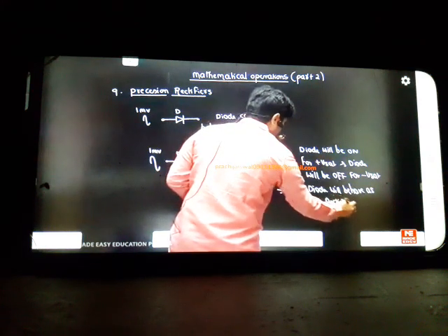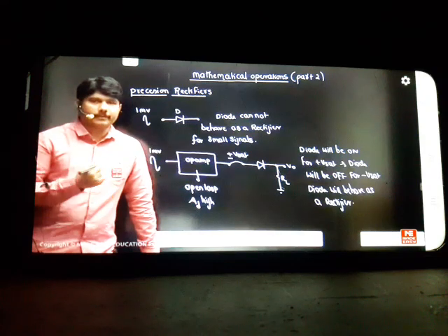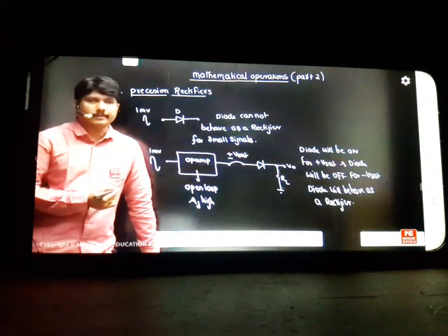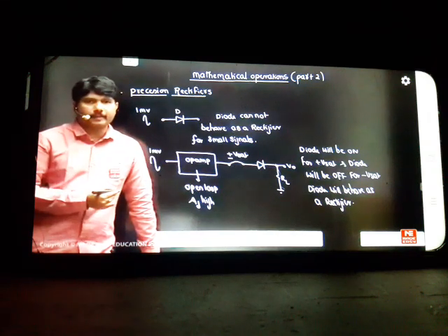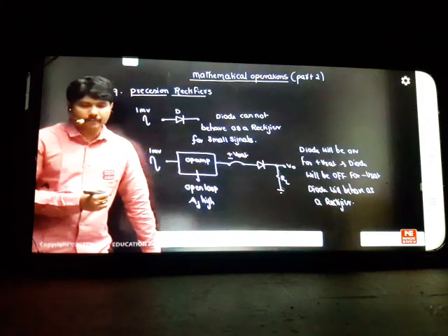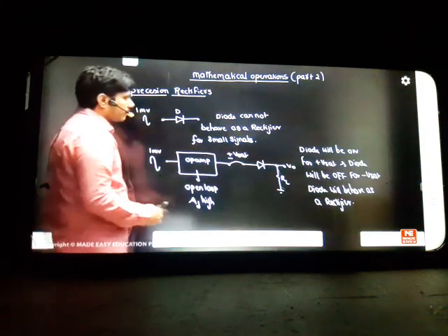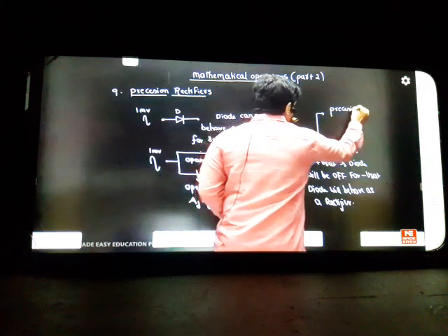So this is actually the story of how they apply electronics with diodes. A basic diode cannot do that work, but with the help of op-amps, if you use the principles of open loop system analysis, automatically the diode works for small signals also. For small signals also it is a rectifier. Such accurate rectification for small signals, we call these systems precision rectifiers. Accurate, we call it precision. Very small signals also the systems will rectify. That is a beautiful concept. Precision rectifiers.